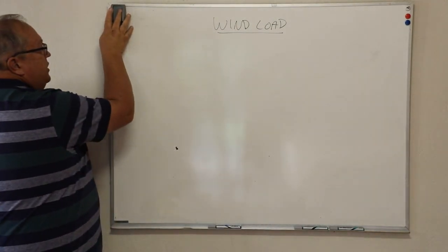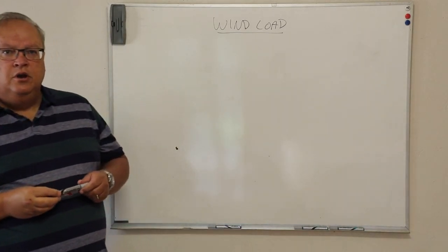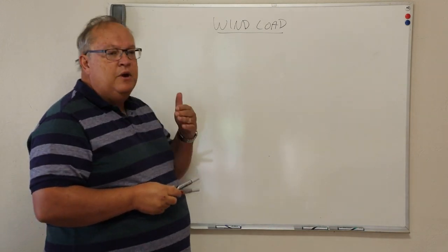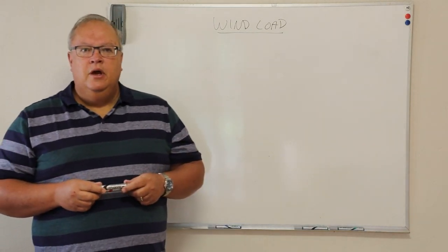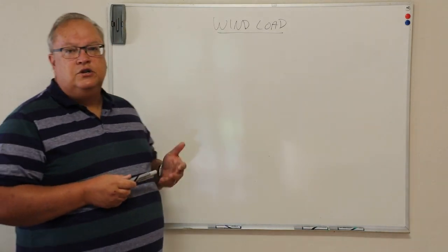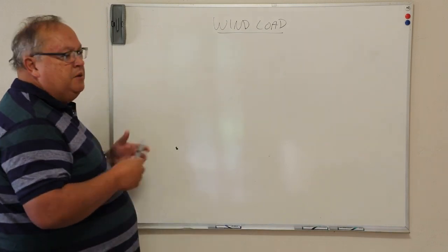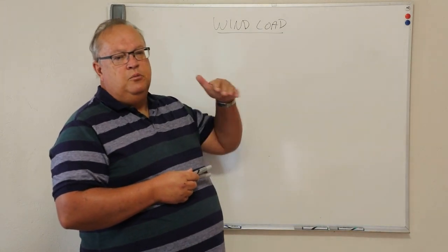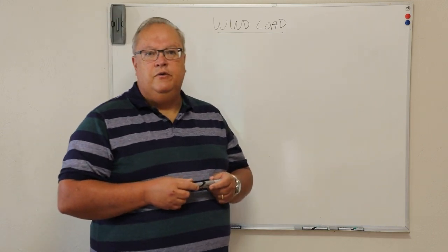Now we need to answer the question, how do we determine the wind load on a particular project? Well, first and foremost, you as a manufacturer are not allowed to specify the wind load on a job. And in fact, the only person who is qualified to specify the wind load is a structural engineer. Now, fortunately, on typically bigger buildings, particularly buildings which the fenestration or the windows are more than 10 meters above natural ground level, there will always be a structural engineer involved.